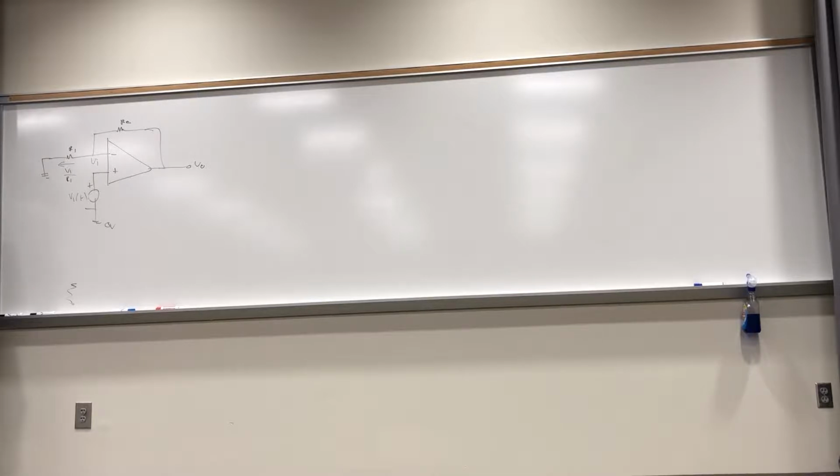Can you see it in the far back there, guys? All right, now, if that's the case, how much current comes out of the negative terminal? 0. 0, always. And when I ask that, it'll stay with you. People have current coming out of there. In the real world, there's something called a trickle current or a leakage current that you'll have to deal with for non-ideal op-amps. Don't worry about this. What I'm showing you works pretty much all the time. Not for every situation and not for high frequency, but for most things.